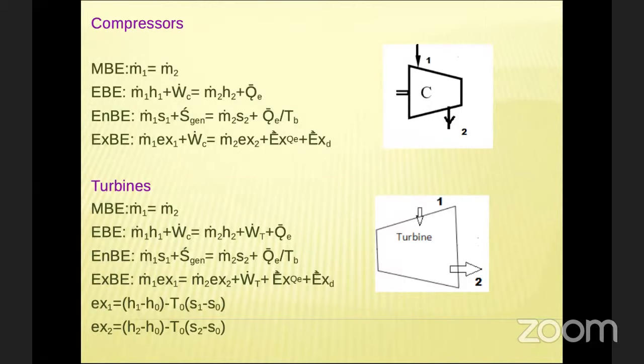Flow rate will be an open system. Another name is flow process, right? So flow means kilogram per second mass. So that is why we are using ṁ. Okay. So ṁ1 equal to ṁ2, compressor inlet and outlet.